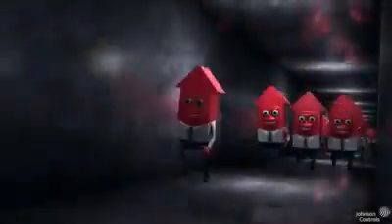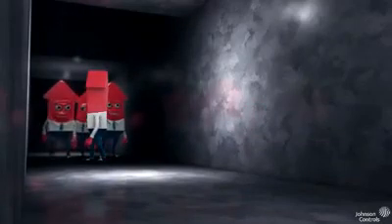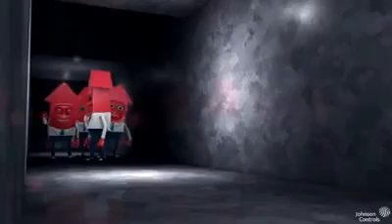Mr. BTU has transferred into the room air, and an air handling unit is moving him and his entourage towards the return air plenum through a grill. This is not a grill you cook meat on, despite the BTU analogies that could be made, but an opening into the space above the suspended ceiling that leads back to the air handler. Entering the air handler, some small percentage of Mr. BTU's buddies wave goodbye through the exhaust dampers. But Mr. BTU and most of his friends re-enter the main airstream, mixing with fresh air from outside.